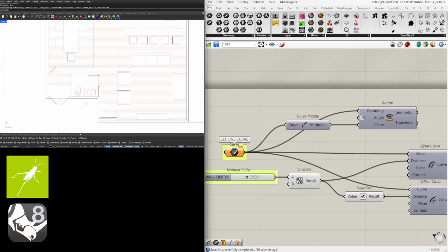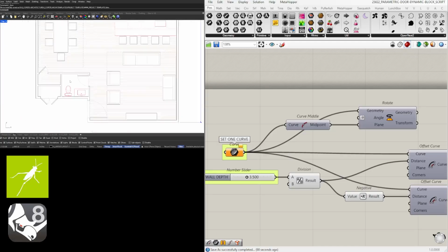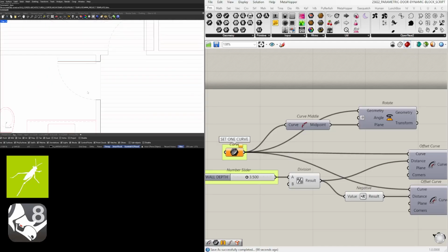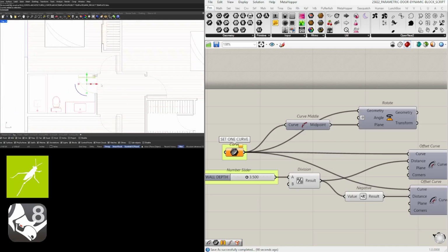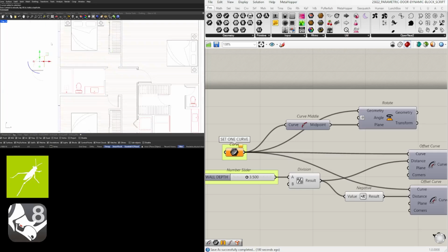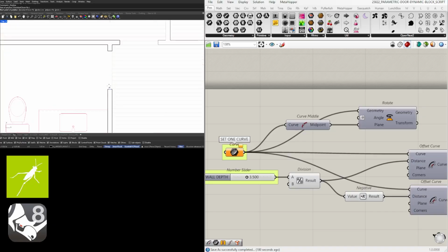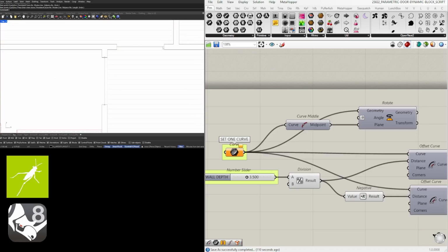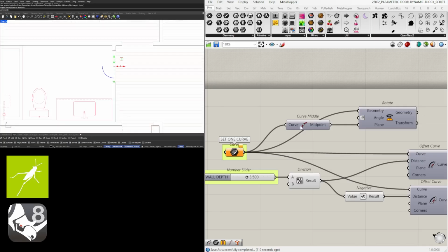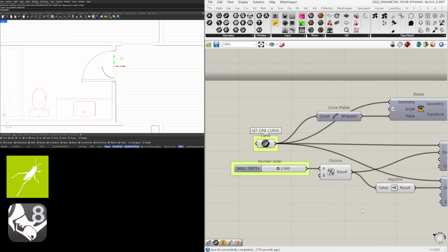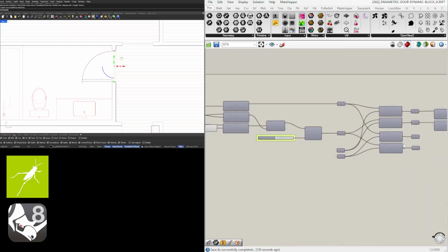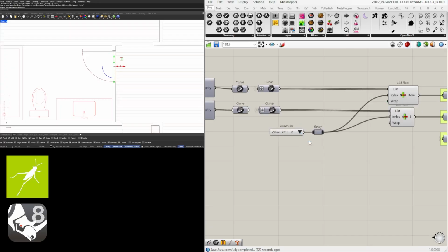So this is a project template that I have, and I already have some doors on this one, but let's pretend like there were no doors here. So let's move this one over here. Let's move this one over here. And then bring in a line segment. So let's go here to a line segment. Now let's say we would just create all the line segments at once, and we can take this and now go here to set one curve. Now we know that that's not the location where we want it, so we'll switch that to 2.